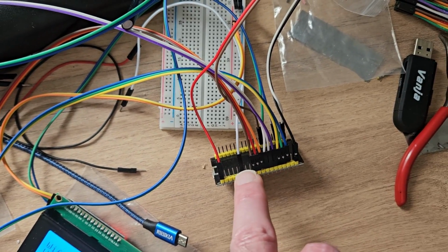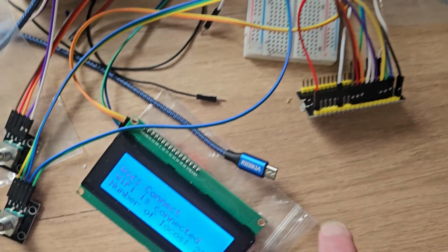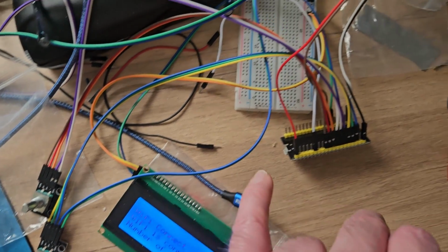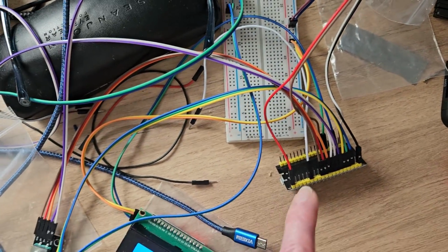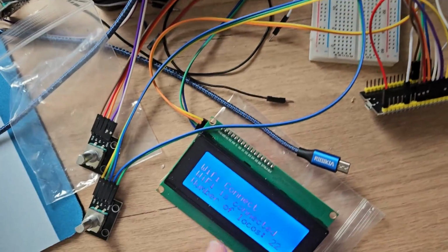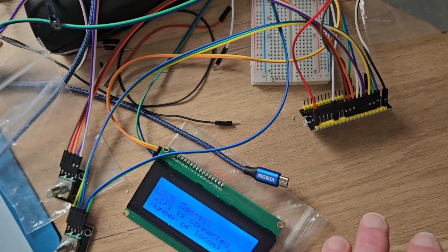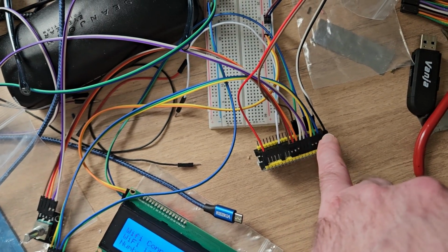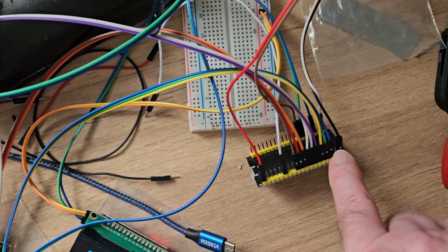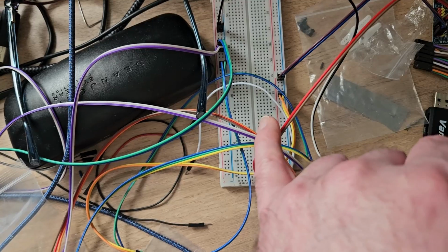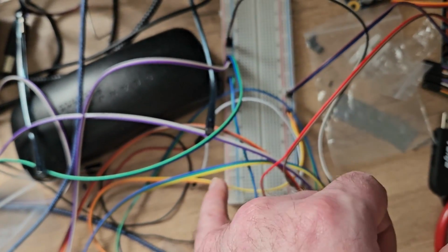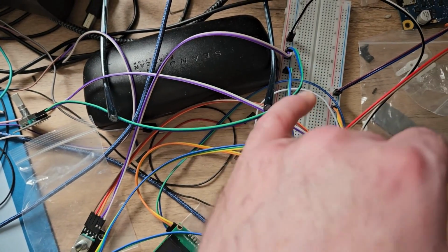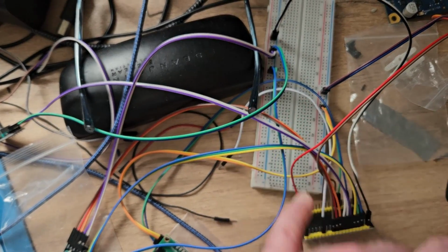So therefore, although the ESP isn't powering the screen, the screen is being powered by the same supply that has a shared ground, and the SDA and SCL cables are going from this into there. So the two of them are happy and communicating, even though they're supplied by the same power supply, I guess. Then you've still got the 3.3 volt and another ground available on the ESP. So that's gone into a breadboard for now, sharing power along a row down there. And all of the knobs are taking their power from that 3.3 volt that's shared on the breadboard.